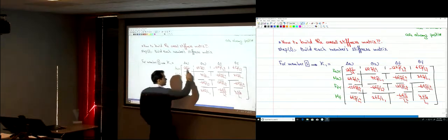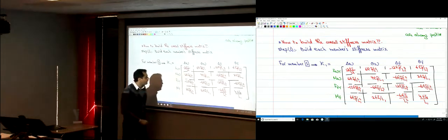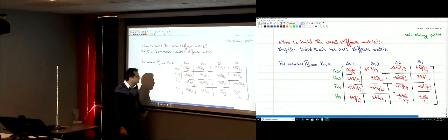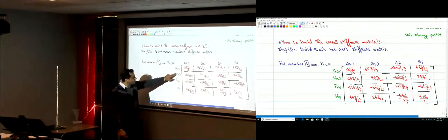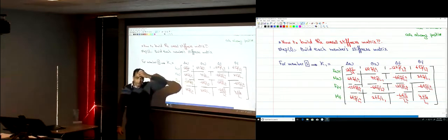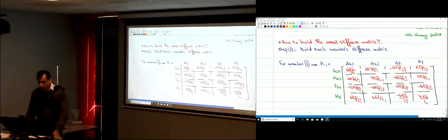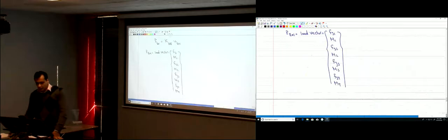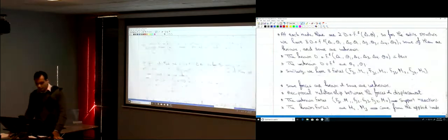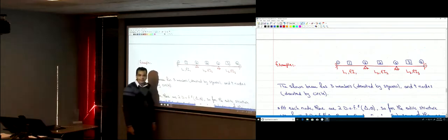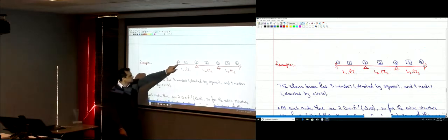What's also different? These numbers of those stiffness elements, we're relating forces to displacements. What are the forces and the displacements? The forces were the vertical force and the moment at the near end, the vertical force and the moment at the far end, and the displacements are similar to them, right? Now, for element 1, what is the force at the near end and the moment at the near end? What did we call those? This is element 1. Where's the near end of element 1? It's node 1.